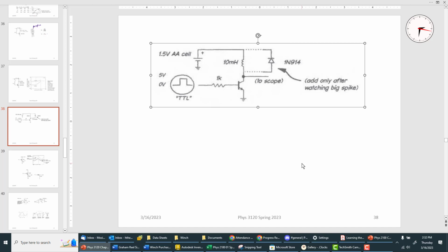And so what you're going to observe is a monstrous spike. And in fact, you're going to attach your oscilloscope to watch this. And so you connect the battery and disconnect it, and you're going to see that it's 0. And let's see, where would you put the scope? Duh. And you're going to notice this monster spike, and then it's going to settle out at 1.5 volts.